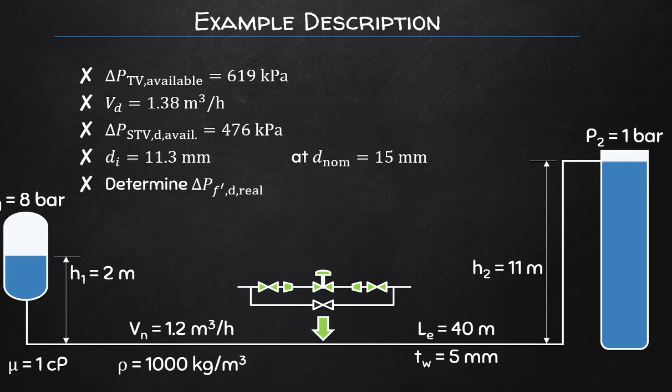We use the real pipe diameter, the chosen nominal diameter available to us, again just to check the frictional loss so that it doesn't end up being too big or too small. Remember, we have only a certain available energy difference that we can utilize here.